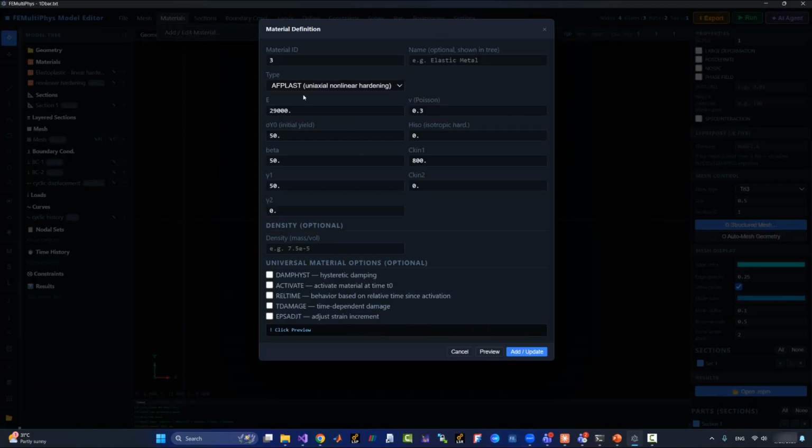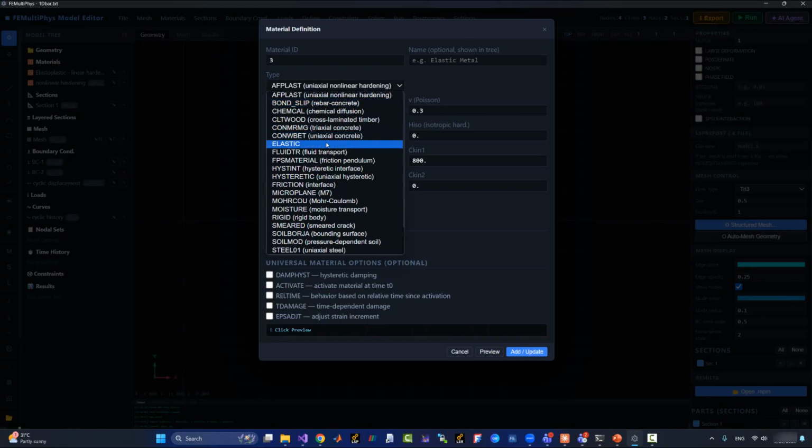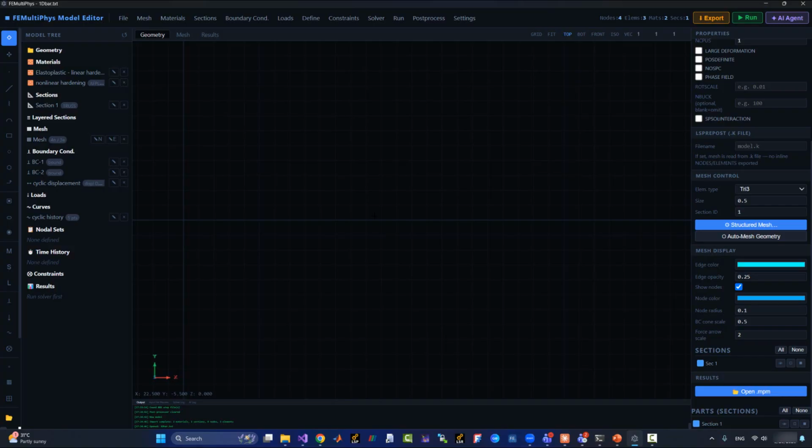So you can see there are various options, lots of them. You can use a generic hysteretic material. You can use material models for reinforcing steel. This is the one that I would definitely advise. It's the most refined one, the steel DR. That's a uniaxial reinforcing steel material. You can use a Menegoto Pinto uniaxial steel material and whatever.